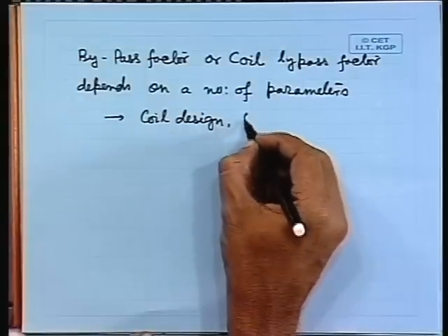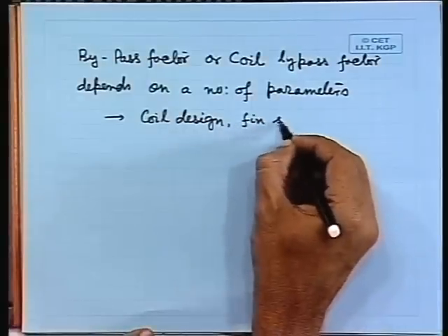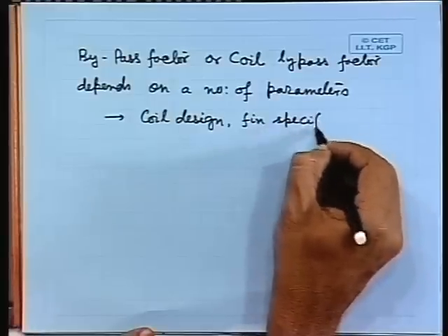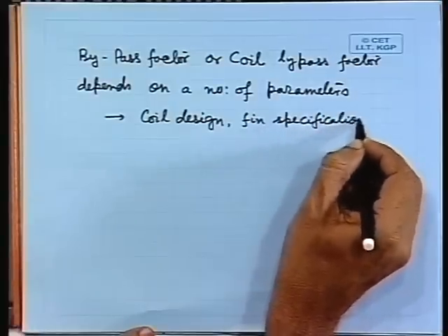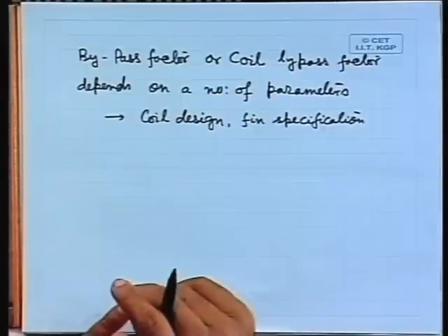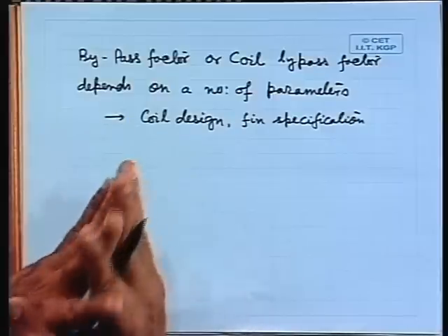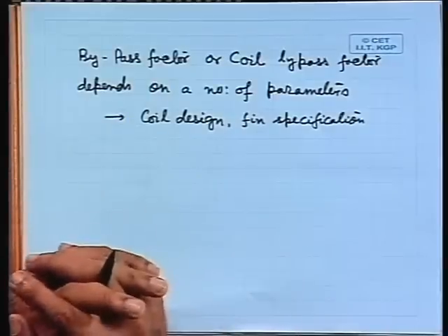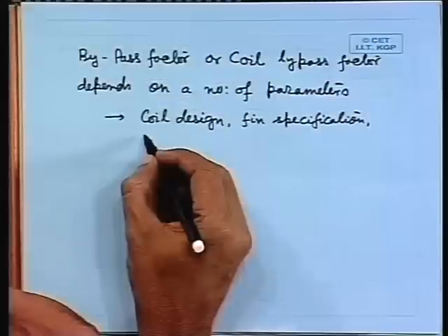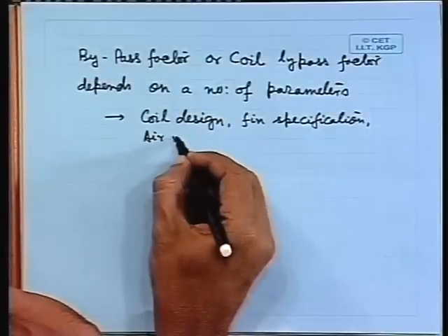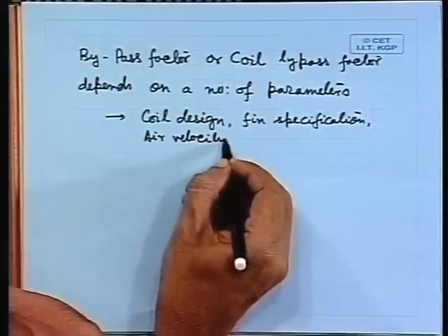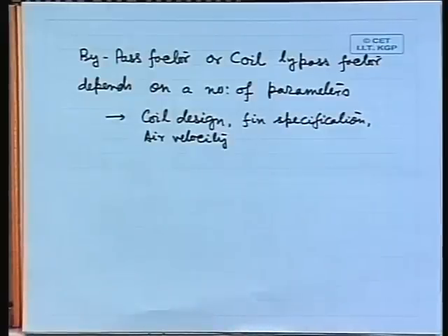Then the fin specification, this is very important, whether you have only a few fins or a large number of fins very closely spaced, what is the fin material, etc. And the air velocity. The bypass factor depends on these parameters.